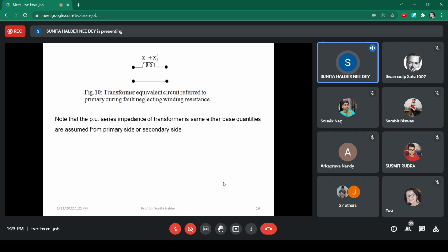One more thing I have not discussed here is the representation of the transmission line. I have already discussed that during the representation of the per unit system. Similar to the transformer, the shunt capacitance part of the transmission line representation has very low contribution during a fault, so we neglect that shunt part. All these things we do for ease of computation, nothing more than that.